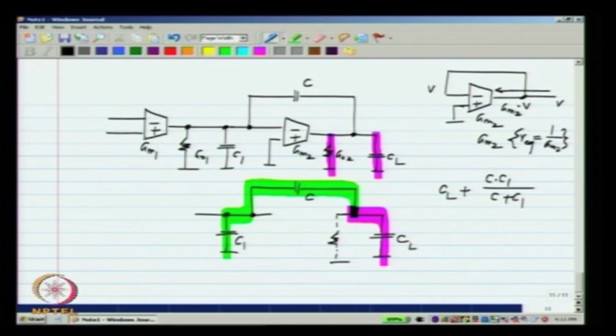So, something like this must be happening, that is the transconductor is in feedback, and that is why we are ending up with a conductance which has a term containing the transconductance GM2, and clearly there is indeed feedback here. You see that there is feedback with C and C1 around GM2. Now, I will draw only that part of the network.